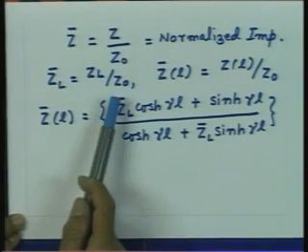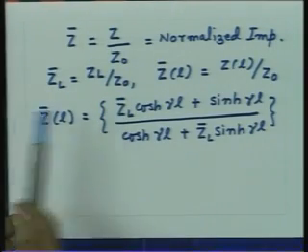So, the important thing is, on transmission line calculations, the absolute impedances do not mean anything. The impedances which are normalized with respect to the characteristic impedance have some meaning. What that means is, if I have a transmission line whose characteristic impedance is 50 ohms, a 100 ohm impedance is going to create the same reflection as if the transmission line was of characteristic impedance 300 ohms and the load impedance is of 600 ohms.